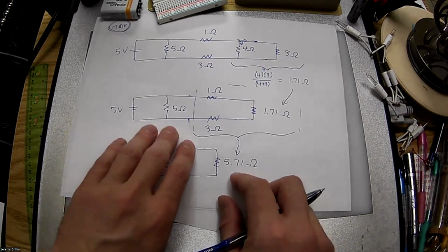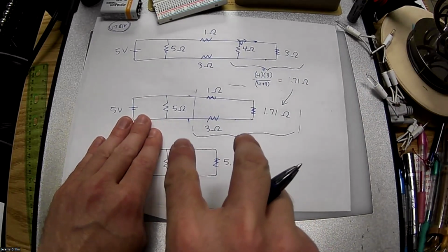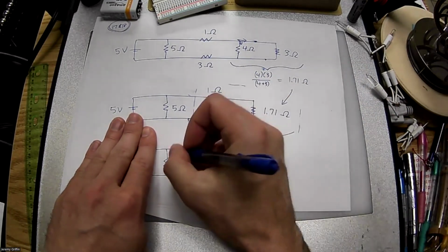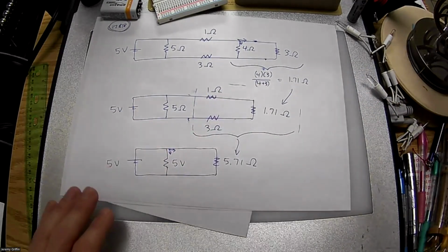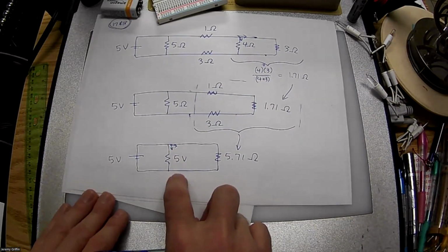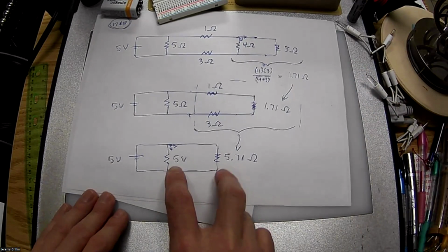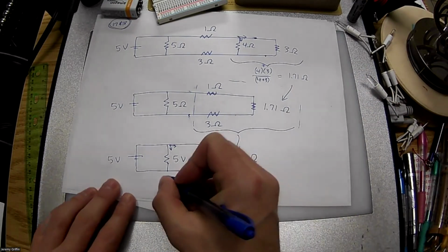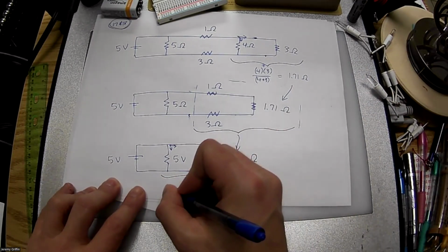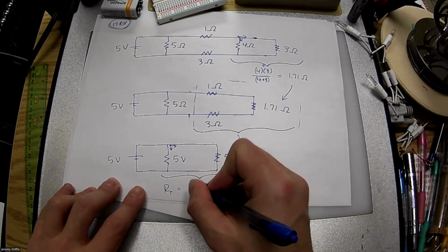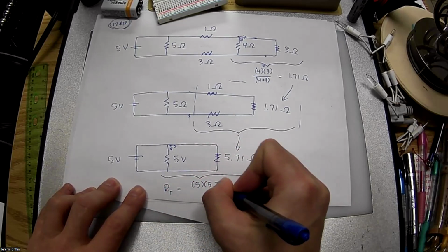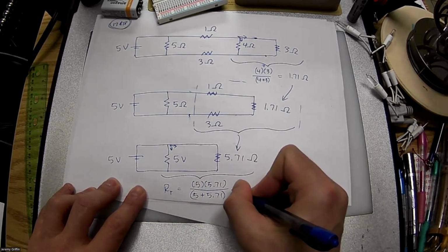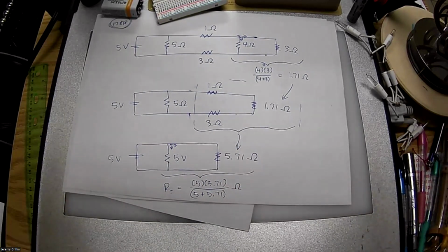All right. Now working back towards the source. Finally, these 2 resistors, is that series or parallel? Parallel, right? Because the current splits, pushes through both simultaneously. If it took this guy about 5 hours, this guy about 5 or 6 hours to paint a fence, I bet together it's going to take somewhere between 2.5 and 3 hours to paint the fence. So let's do product over sum and figure out the equivalent resistance for the entire circuit: product over sum of those individual resistors.